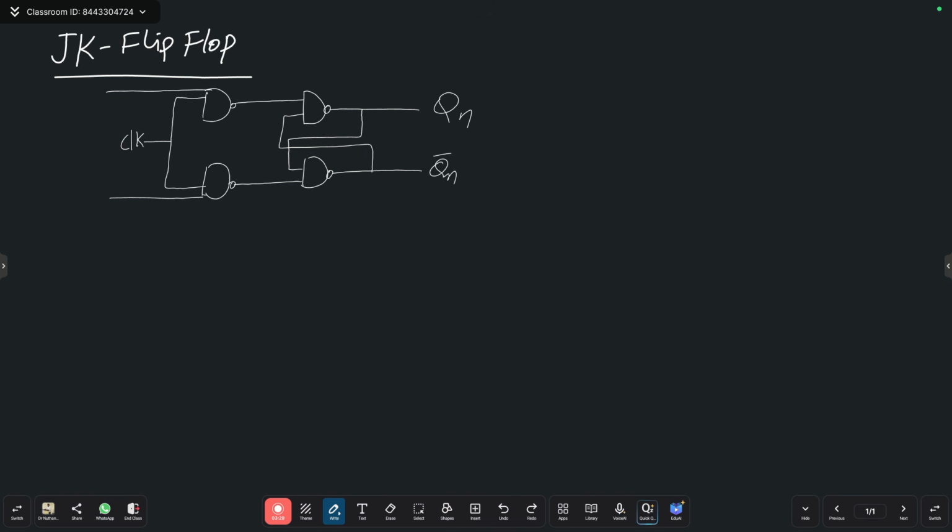So in the JK flip-flop, we have the 4 states. Out of that, one state is an indeterminate state. That indeterminate state you try to convert into a toggling state. Are you clear? So again here also you will get 4 states. No change, set, reset. In place of indeterminate, we are going to do toggle.